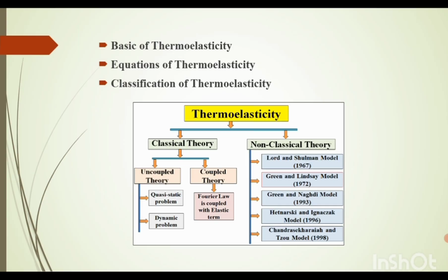This hypothesis has two flaws. First, there is no relationship between temperature and the mechanical condition of the body. In second place, practical investigations contradict the parabolic heat equation's implication that the pace at which temperature propagates is unlimited. To solve the first constraint, Biot in 1956 developed the idea of coupled thermoelasticity. This theory connected the governing equations, solving the classical theory's initial flaw, but because the coupled theory heat equation is similarly parabolic, there is a second flaw in both theories.